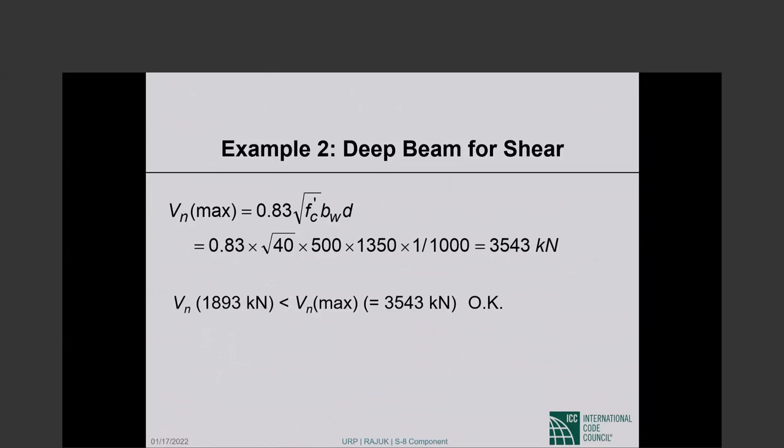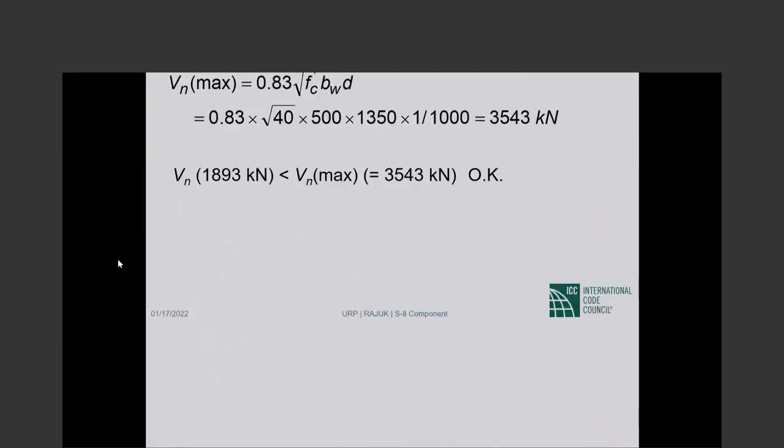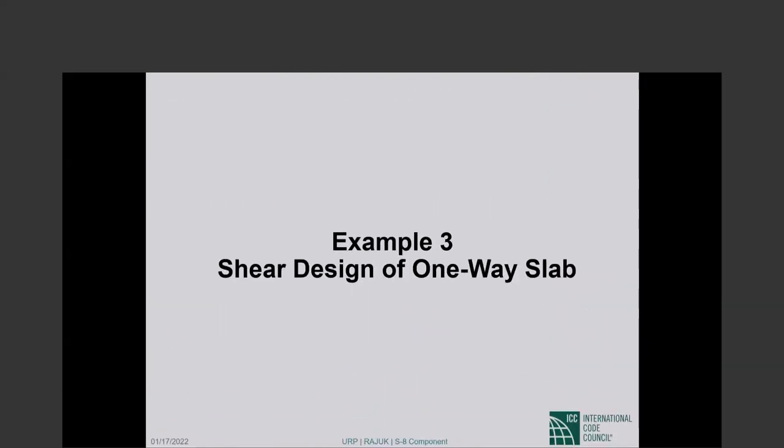So the shear does not exceed 10 square root of f sub c prime, so we are okay on all counts. So this is a complete design of a deep beam. As I said, you will not find it all that commonly anymore. This was last in ACI 318-99, so I thought that I would show it to you.